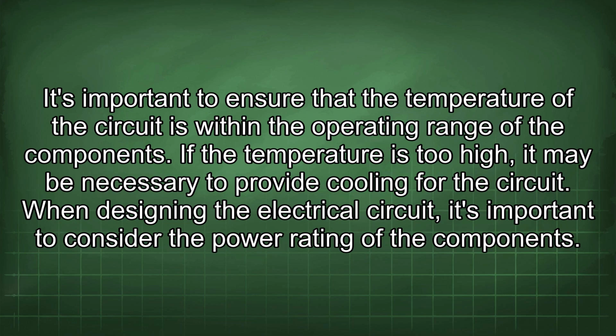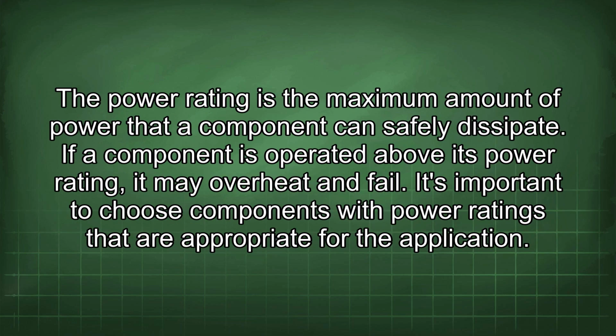When designing the electrical circuit, it's important to consider the power rating of the components. The power rating is the maximum amount of power that a component can safely dissipate. If a component is operated above its power rating, it may overheat and fail. It's important to choose components with power ratings that are appropriate for the application.